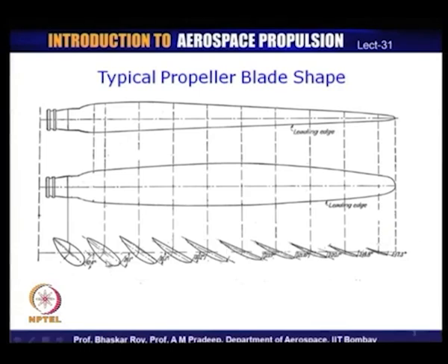Another thing you would notice is that near the root of the propeller, the angle at which the aerofoils are set is a high angle. For example, near the absolute root, which is actually inside the root, the angle is nearly 42 degrees, and then near the next aerofoil, which is a proper lift creating aerofoil, the angle is 39.5 degrees, nearly 40 degrees.